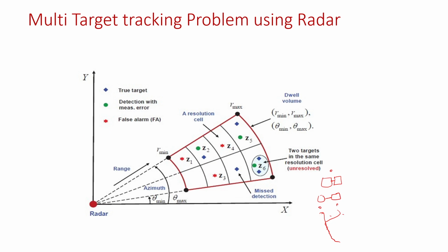So, in a 2D scenario, this is range and what is called the azimuth cell. You have seen, it could be multiple things. In this example, you have a false alarm here, there is no target present in this cell. Here actually there is a misdetection. You have an actual target present, but the sensor failed, so you won't have any update.